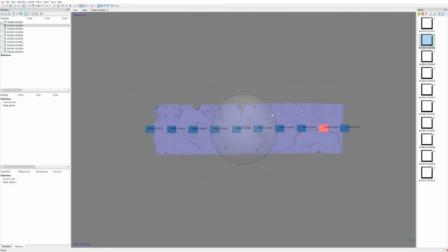Before I move on, I'm actually going to resize my bounding box, and if you come up to the top and hit this drop down, you can say resize region. The reason I want to do this is I don't want to process any more data than I have to, and also the town is really only on this left side, so I'm just going to remove all that stuff on the right to save some space later on.